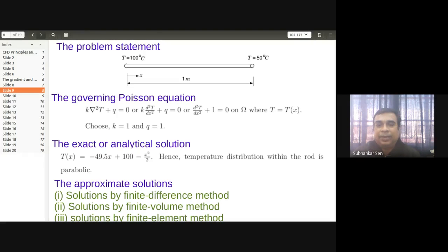It means that whatever the perturbation, heating or cooling, you implement at a particular point, that will propagate with the same intensity in all directions. So this transport of heat, diffusion, is isotropic. This is the point I want to make: heat transfer by conduction is isotropic. It is not a function of direction. So heat waves will move in a spherical waveform.